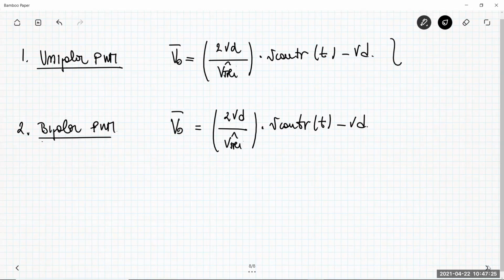Again, we can consider this as a general solution for my four-quadrant converter for the output. We can define K, let me call this KPWM, a constant, 2 times VD over the peak value of the triangular waveform, which are constant parameters. Remember that we have the K-pole, the constant appearing in the VAN average value expressed for the two-quadrant converter.